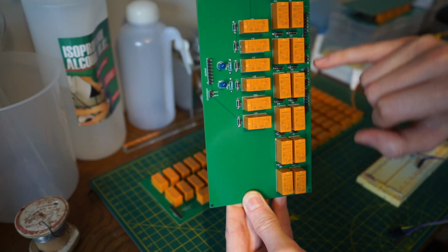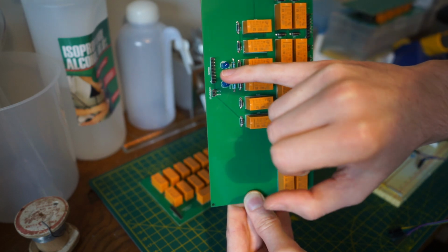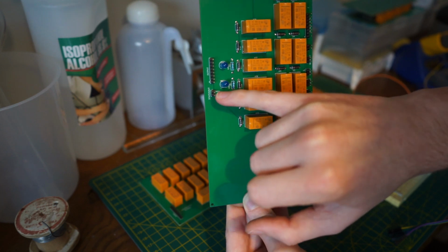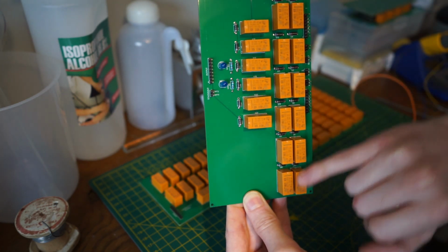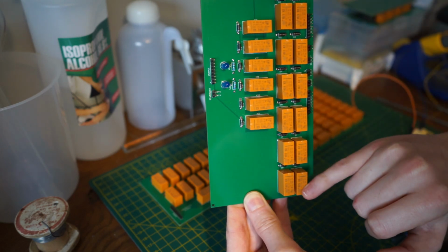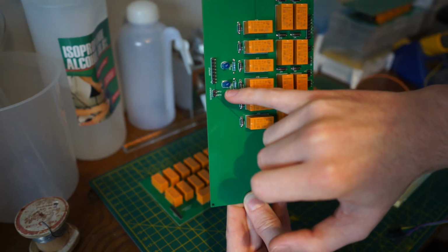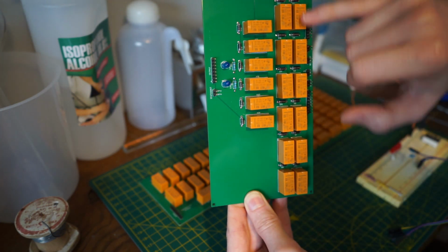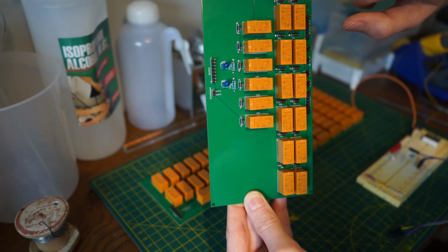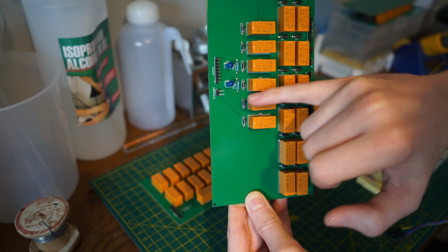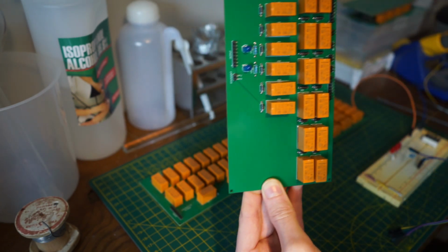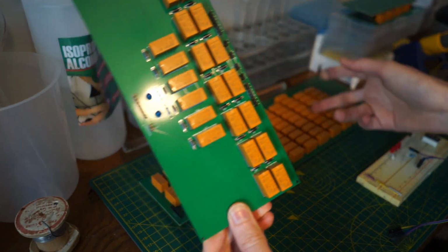So if there's a carry and you do the set, you'll get a flag which is going to be carried out on these 2 pins. And in here you have basically a chain of relays. If a single one of the inputs is on, it breaks the chain and the 0 flag cannot be turned on. But if all of the inputs are 0, then the chain of relays is not broken and it will output a 1, which will then be latched if you do the set. So this board basically puts together everything from the other 2.